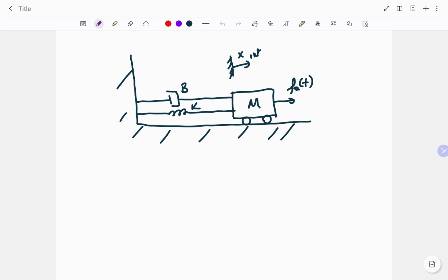So because of this, as a first step, we should decide our state variables for the system. What are they? For such a system, it should be the displacement and the velocity to describe the storing elements of the dashpot and the spring in terms of the equations. These are related with each other.